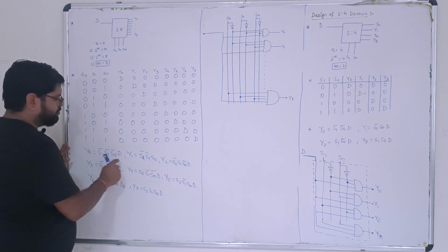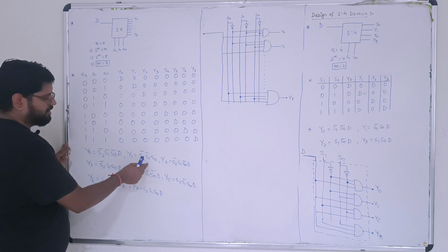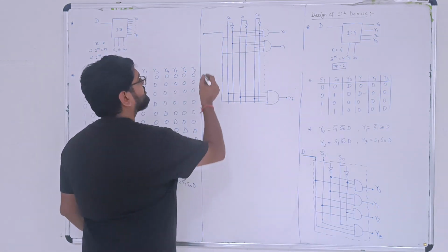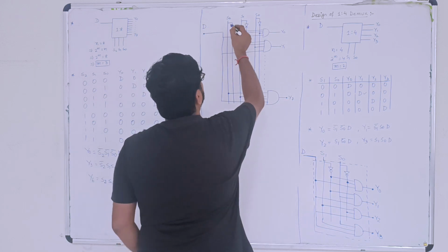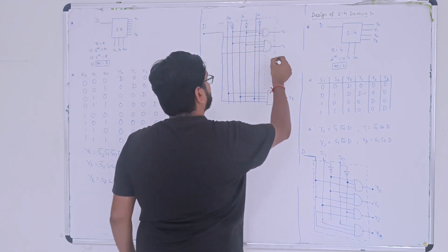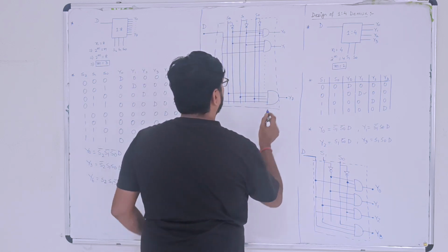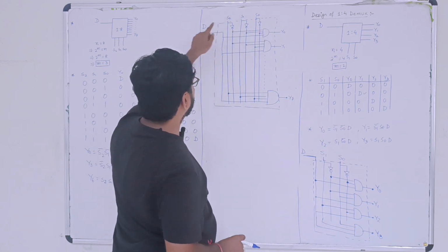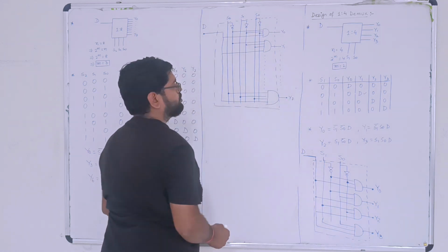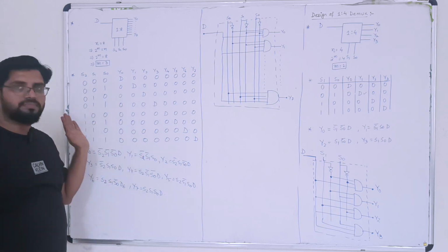After that, write down the binary equation of each of the outputs, and after writing that, you need to follow this process, and by using this one, you will be able to design the DeMUX. Now, if you look at it, you will be able to visualize that it matches the initial diagram that we have drawn. So how many select lines will we have? 3 select lines, 1 data input, and 8 outputs starting from Y0 to Y7. So this is all about the demultiplexer design.